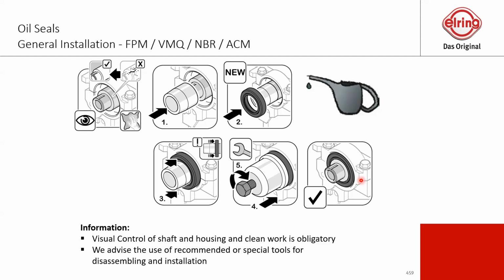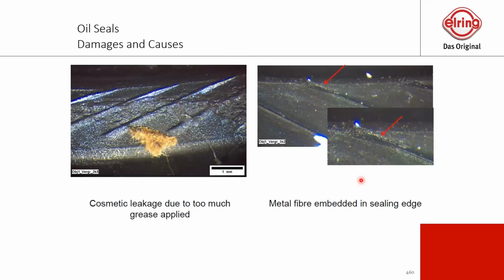Why should you not use anything else, like grease, for the lubrication on the oil seal? It's quite easy. If you use, for example, a grease, then it gets sticky. And if you have stickiness outside of your flank, then you will cover it up maybe with dirt, or whatever is flying around. This twist that we have here, you don't want to cover up, because otherwise this vacuum effect doesn't work as it should. So that is the thing you should avoid. Use a thin motor oil, or any kind of Teflon spray, whatever you like. That's also fine, but no grease. This is really what you should avoid.